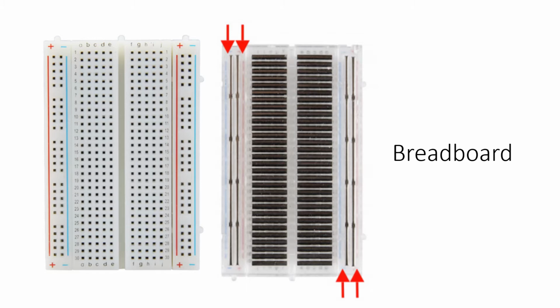So we can put a lead across from, say, A1 to here, and then we can bring power in through this bottom hole, and that will bring power to the plus up here, to that hole, and then into this resistor that we brought in from A1. And I'll show you examples of this in a minute.